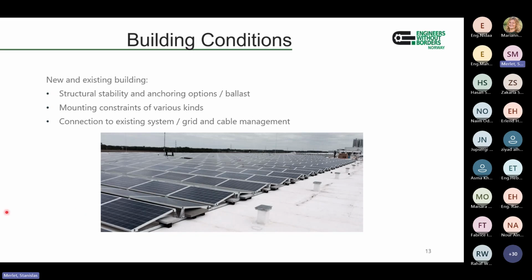Next question was what is better, to mount the panels vertically or horizontally in the same area? It depends a lot on your mounting system. Both options are very available, but I do prefer the landscape one, especially for ground mounted. And this is for the reason that Michel explained on Monday.